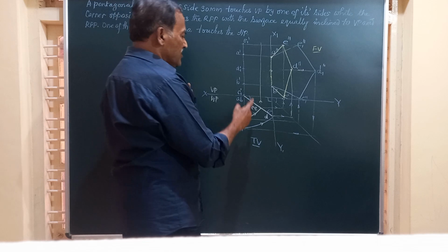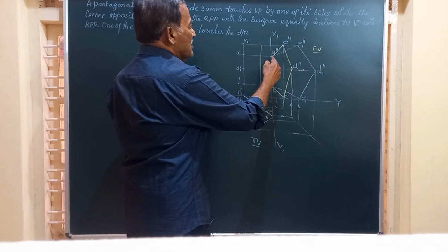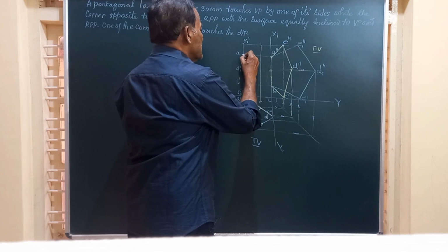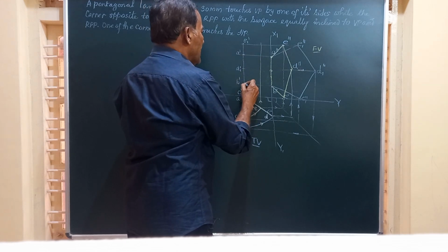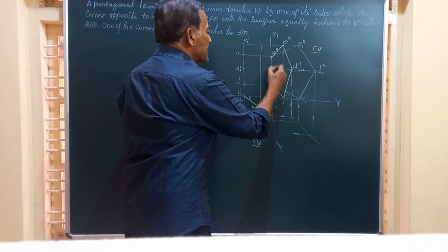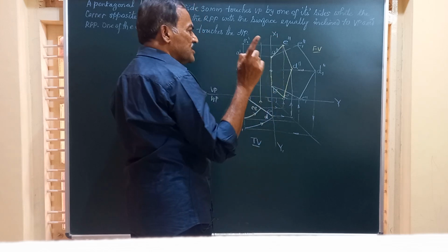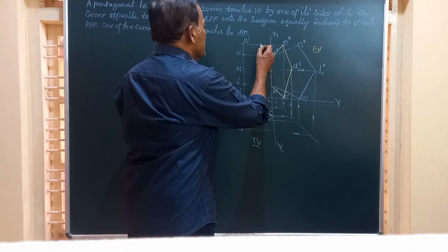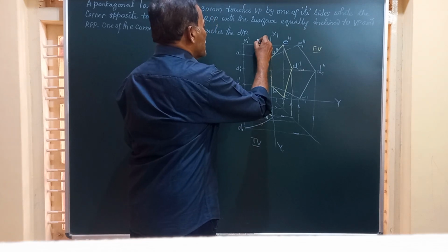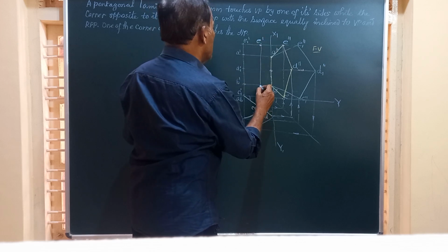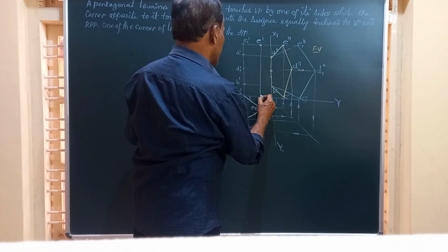After obtaining these points, let us obtain the final front view of the lamina. Friends, see here you have got this lamina, that is end view on this XY. So this is going to be final A and this is final B. Next D. D will be exactly on this because it is touching the right profile plane. Then friends, you have got C and E. E comes here. So I will call this E dash, and this point is going to be the corresponding C dash.